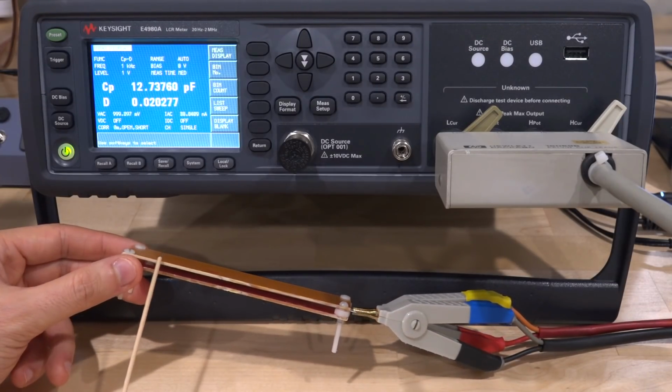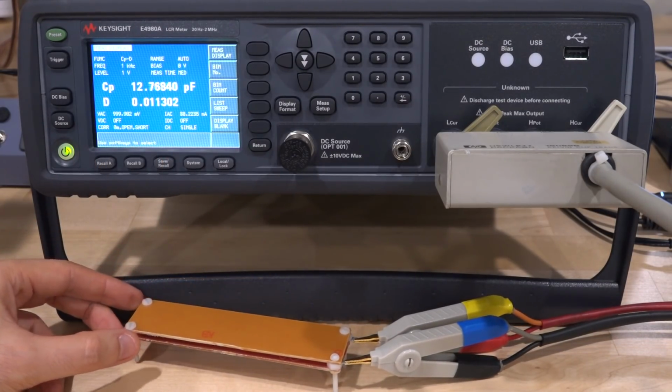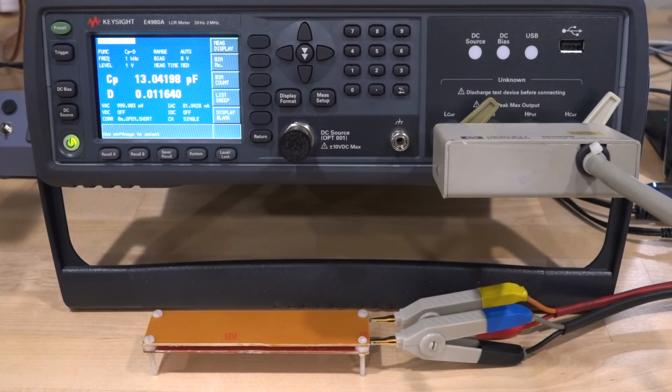But what is fun is to put different kinds of materials between this. And if you can measure the capacitance, you can tell what the dielectric constant of the material is, and you can also make some other interesting conclusions. Okay, so I added a factor of 4 averaging as well. Now let's take a look at this little piece of wood. Now this is tiny in comparison to the total area of this capacitor. But in theory, if I put this between the two plates, because its dielectric constant is more than air, on average it's going to increase the capacitance by just a tiny amount, because the electric field going through this is going to be different than going through air. Let's try that. Now this only really is possible with a very accurate and sensitive LCR meter. This is of course one of those.